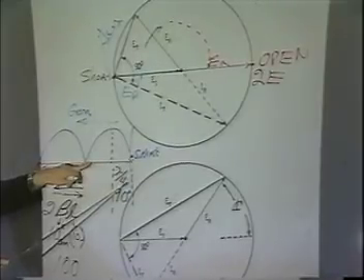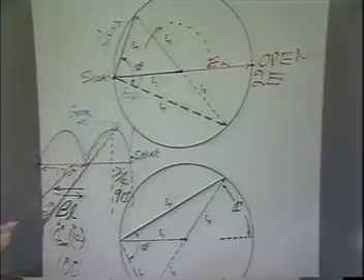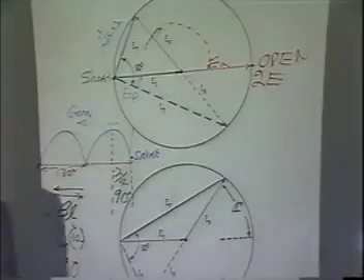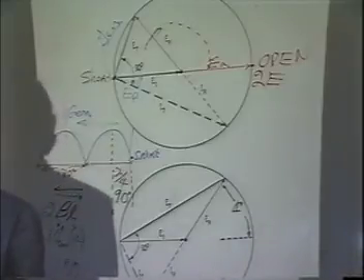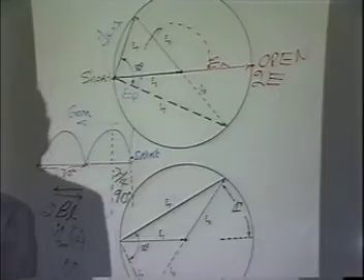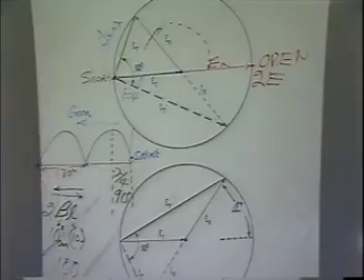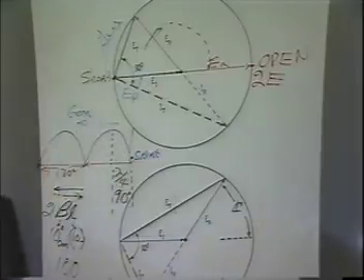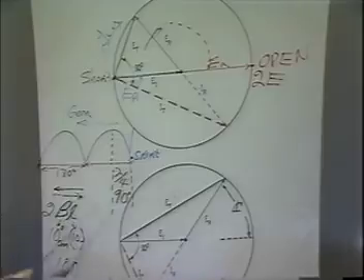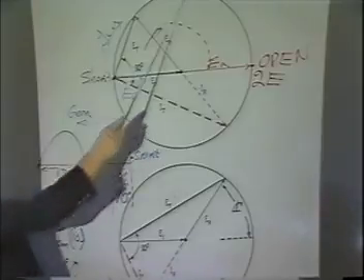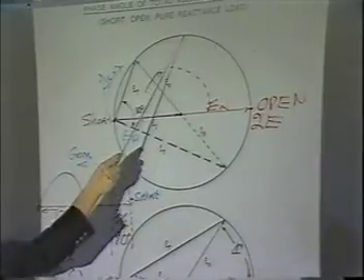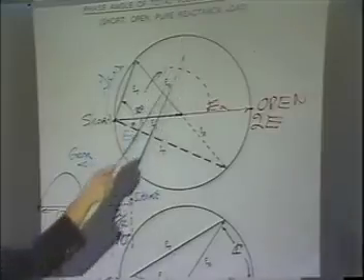Then what happens? If you keep going toward the generator on here, you just keep going clockwise around the chart. So how many times around the chart will you have to go in order to go one wavelength? Twice around, right. Because each time around that chart is 1/2 wavelength. So now we have a way of equating. If I say this is 0.1 wavelengths, then this would be 0.1 wavelengths up here someplace. If I say this is 0.15 wavelengths, it's 0.15 a little over here someplace. Right? This would be 0.125, which would be halfway here.